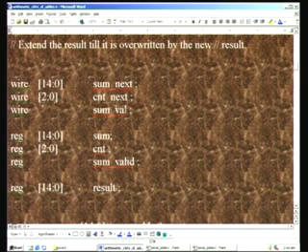And we also need to declare sum valid, which is basically the same as this sum valid, with a note of the difference in spelling here, and this is an assign statement, that is why it is declared as wire here. And we also finally need the computed sum, and that is 15 bits as we have already seen, and it is going to appear in the always positive edge clock block, and therefore it is declared as a reg.